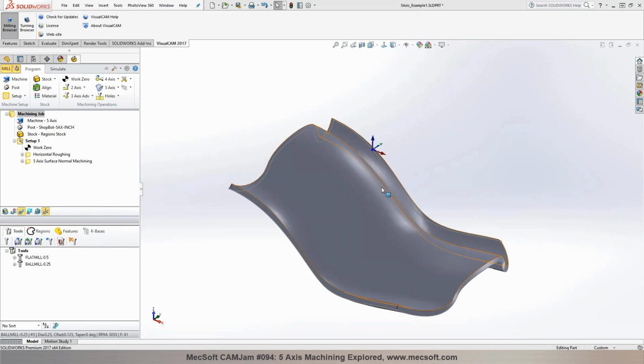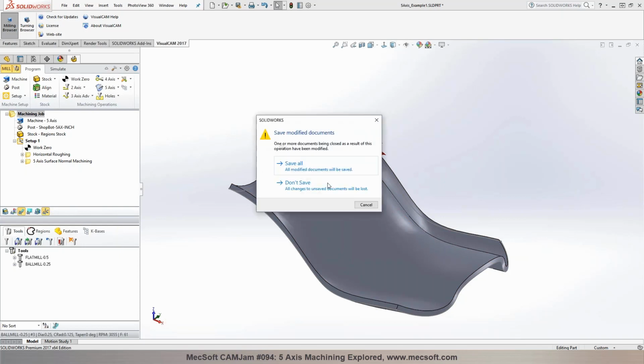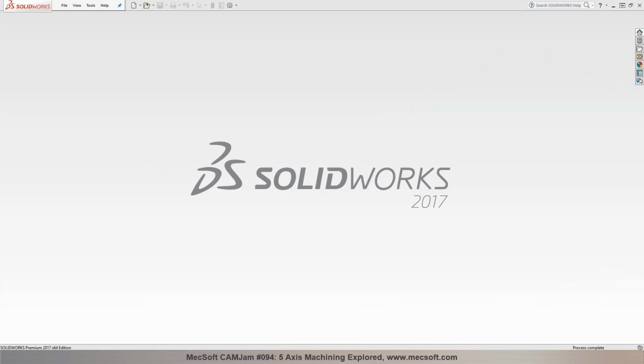But what if, for any reason, this geometry is created by the addition of one surface here, another here, another here, three surfaces? I need to select all those three surfaces in order to machine this part. Yes, you would select them as either a drive surface or a gouge surface, depending on what surfaces you would like to machine. Now, for example, I'm going to pull in another example in here, and we'll take a look at that as well. Just give me one moment here.